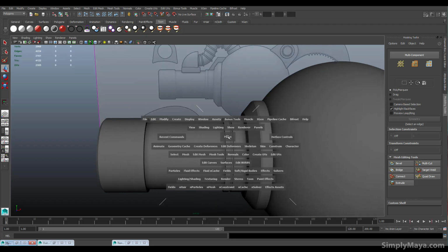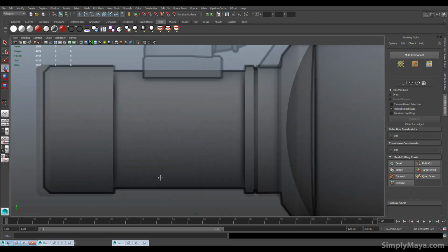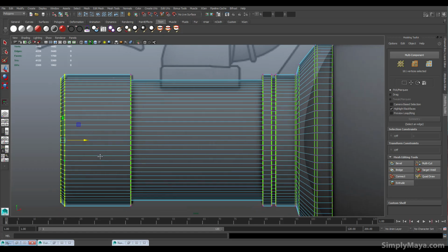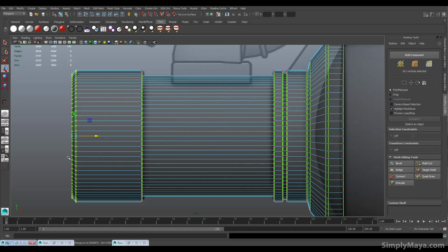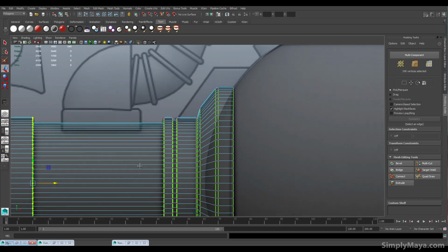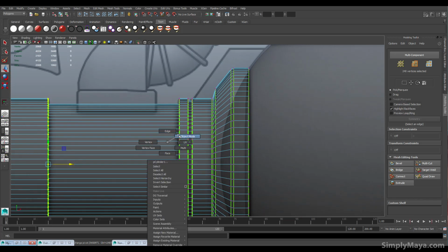We just check that we've got everything we need, and I'll disappear back into this view and check that it matches the reference. If it doesn't, of course, you can do some adjustments. Now, the bevel that I had on the reference object was obviously bigger, and you can just adjust that in the bevel settings. This was a bit this way, so sometimes you'll need to come in and do some tweaks, and this matches, so that matches.